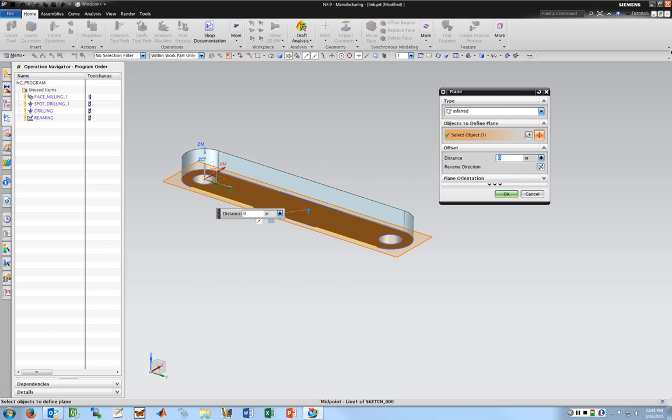If I leave it at 0 inches, whenever you machine a part like this, if I'm trying to cut it out of the blank that I'm machining, if I cut through to the bottom side of the blank and then machine around this, as soon as the machine gets through cutting, this part's going to be free from whatever's clamped down, and it's going to go flying, or it's going to bind up and break your bit, or it's going to bind up and damage your part. So what I generally do is I can leave it a little short and then take this whole thing out, bandsaw it out later, and then clean it up.